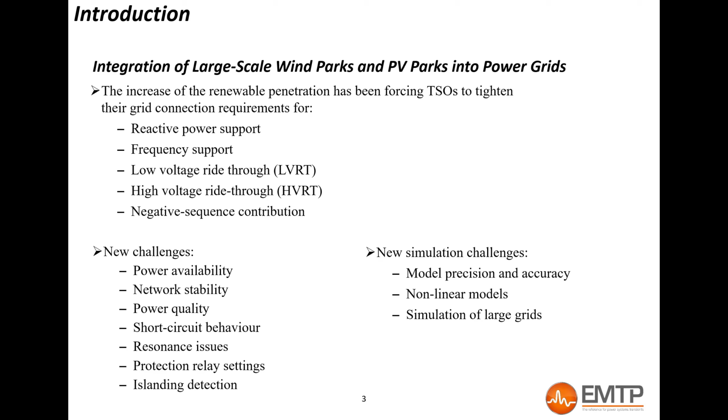In terms of simulations, to be able to simulate and study wind parks and solar parks precisely, new models have to be developed, and now I can say have been developed because it's done. Of course, there's more work to do to improve generic models and manufacturer models, but I think now we are getting to a very good place. The models have to be precise, and the simulation software has to get more precise. The industry is slowly shifting to use more and more EMT-type software in order to simulate precisely those renewable energy integrations. We have to be able to simulate nonlinear models and very, very large grids in EMT-type software.